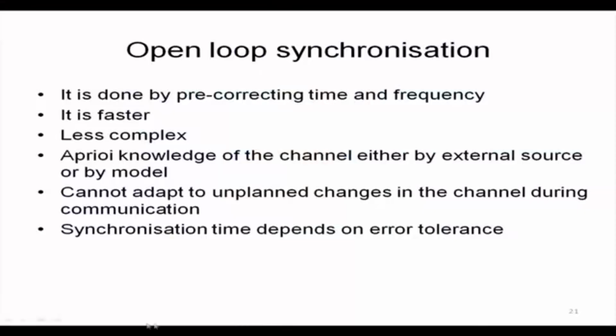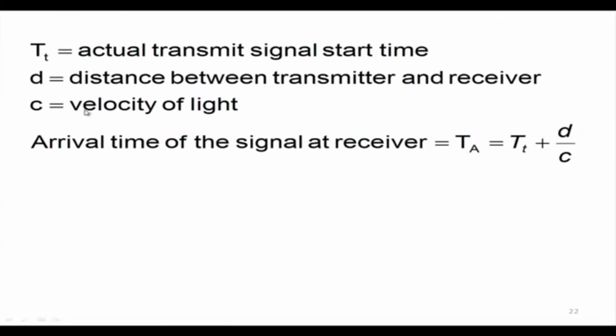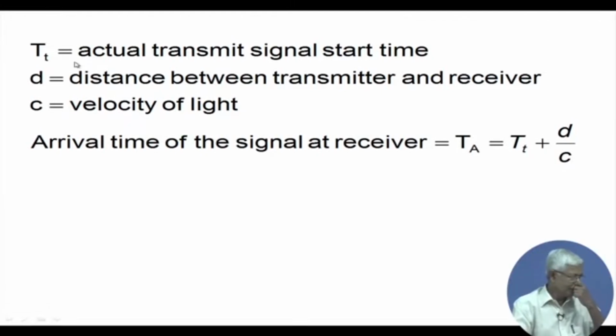Welcome back. We were discussing synchronization, and we have covered frame synchronization, particularly the unique word detection part of it in the burst. Then we just started on network synchronization, and in network synchronization we talked about open loop synchronization. Then we were starting on open loop synchronization in terms of time and frequency.